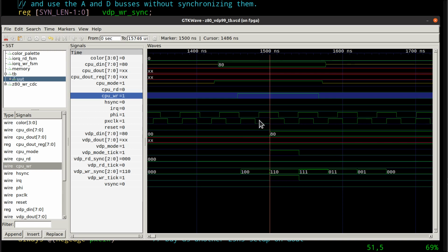Now, if this thing fires any earlier, actually it can't. This is as early as it can ever go, okay? Because this rising edge is right after that one. It could go as much as all the way over here in a latest scenario, and you can see that the data and everything is still valid, and these are realistic times up here. So this is safe to do.